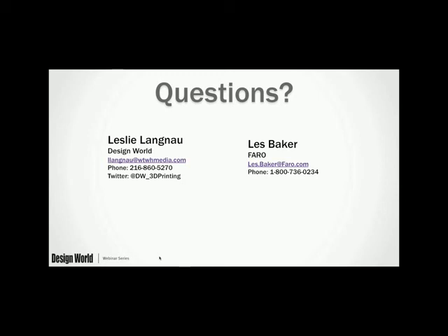So you can get a good feel for whether the accuracy that you're getting is truly representative. If the form is bad, then that means that either the fit of the points is not good, or the cylinder that you're measuring is not good. So it gives you a lot of flexibility to get the data that you need and to understand your part more effectively.